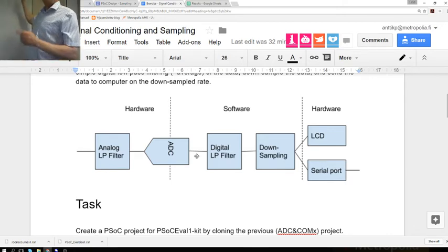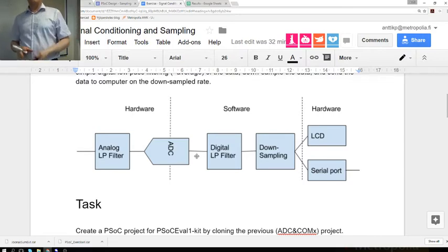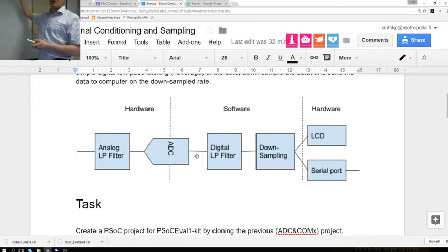Okay, so basically we start switching these on, off, on 90-degree phase. We get control of how fast the charge goes from one end to another one, which fundamentally at high frequencies starts to look like a resistor. And this switching frequency is actually controlling how much current you get through. So the resistance or conductance.